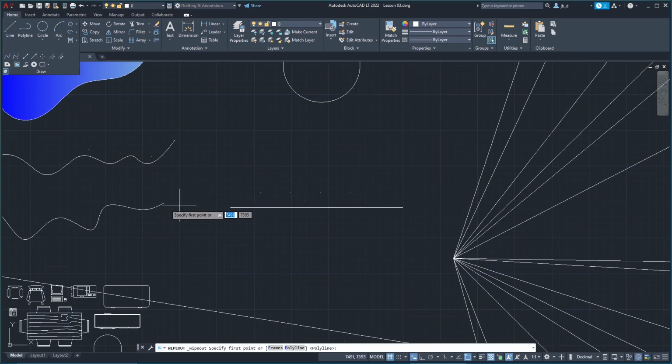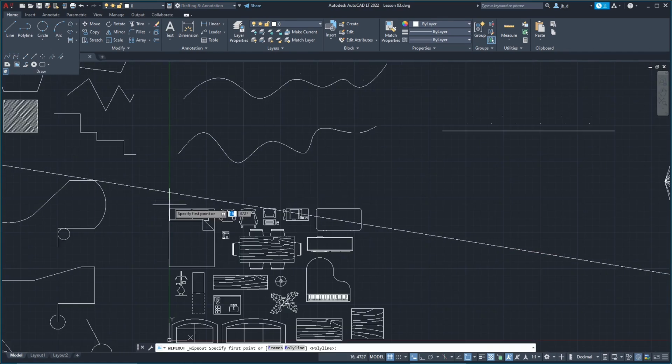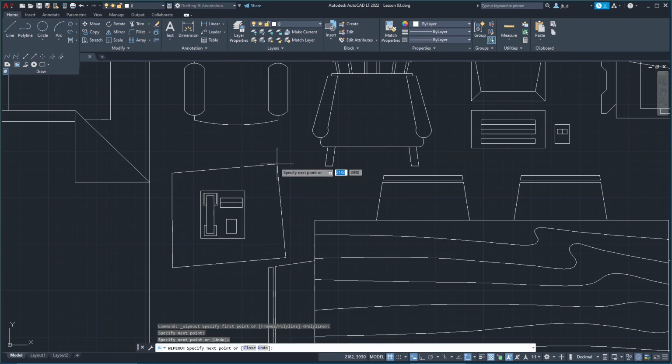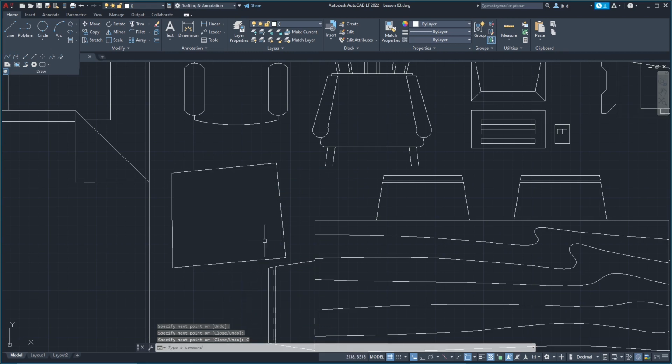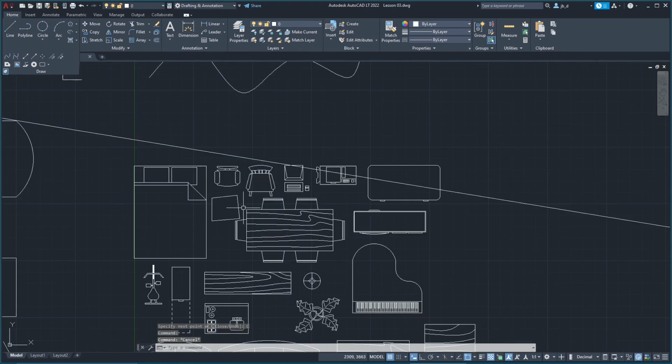Wipeout. Well, this is similar to the polyline. This is where when you want to hide something from the view. So for example here, let me see, I want to hide this phone. I'm gonna click there and create this thing just like a polyline. So I'm gonna close it, and this is applying like a patch above that object. Now you can always arrange things using layers, using arrangement tools, but this is what usually this one here is used for, is to hide something.